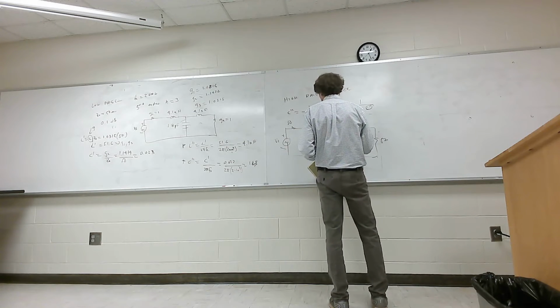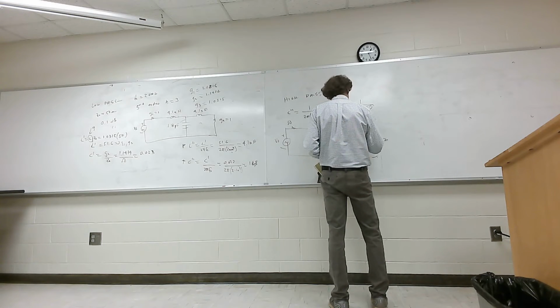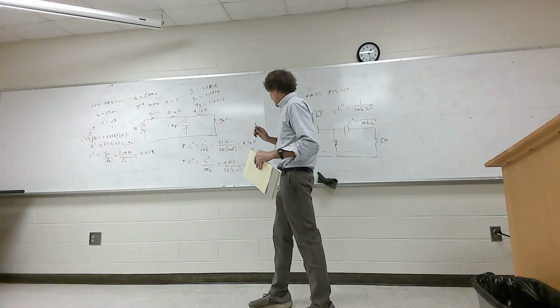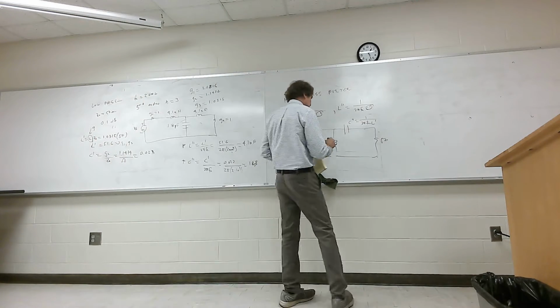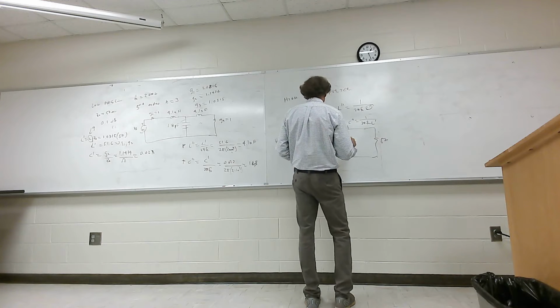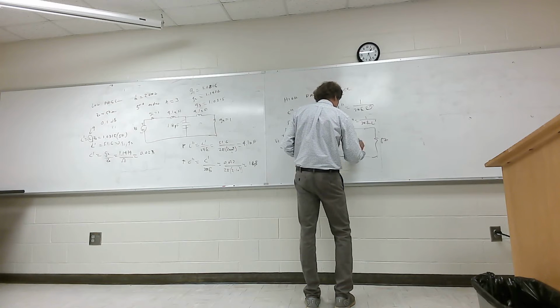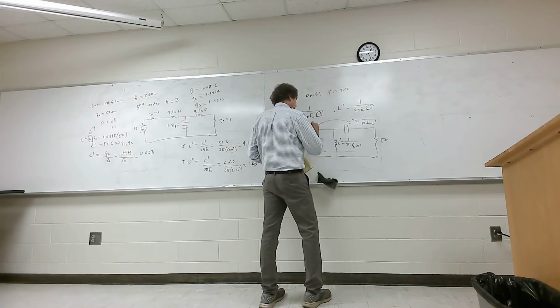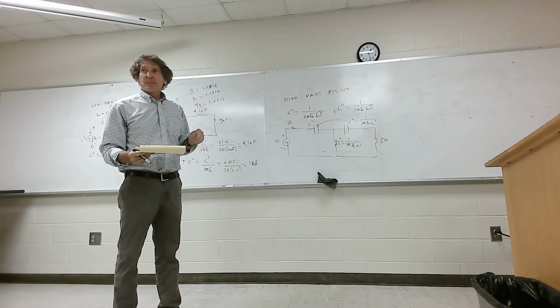And the value for that capacitor right here would be 1 over 2 pi FC L prime. Remember the L prime we had was right here. And for the actual inductor, this L double prime would be 1 over 2 pi FC times C prime. And this would be the same, this would be C double prime there too. And that would be a high pass filter with the same exact amount of ripple.